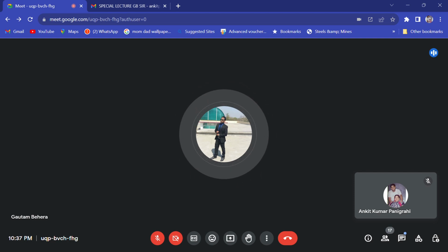Sometimes some slag may be carried over in the steel and it will remain up to solidification. Slag is also a silicate or it may be an oxide, so it is an inclusion again. And during deoxidation practice, you remember when we are removing the oxygen, we are adding alloying elements like aluminium, calcium or silicon. So they become SiO2, Al2O3. These are inclusions, no? Oxide particles. So it is very difficult to remove 100% of inclusions, right?